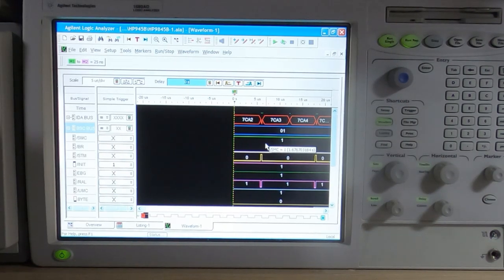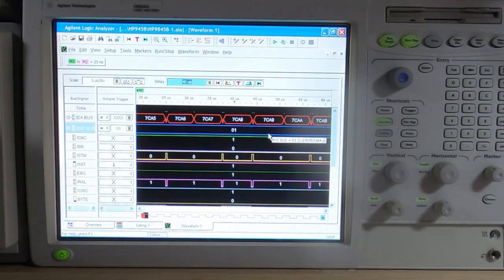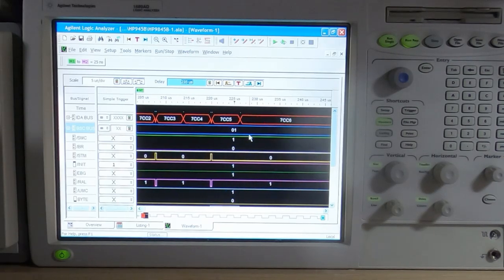and if you recall, the buffer for the CRT display starts at 7000 hex. These are hex values, by the way, and they're in the PPU RAM card, which is block 1. So you can see the block address is indeed 1, and the address is falling within the range we're expecting, and it is incrementing, so we are successfully capturing the data coming through the buffer. So we'll keep scrolling across now.